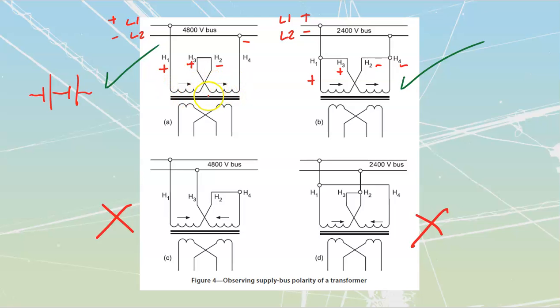That's what they're showing with these little arrows over here, is that those fluxes are working together. In other words, the flux that's created through here is going to join the flux that is created through here and then circle back through my transformer core. If I don't place my fluxes in the same direction, I'm going to cancel them out, right? And as soon as I cancel them out, I'm going to drop the amount of counter EMF. The only thing that's preventing these wires from acting like a short circuit is the fact that we have counter EMF that is operating against them.